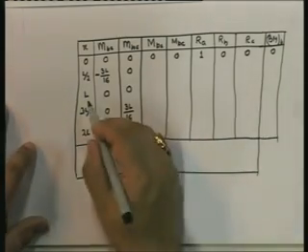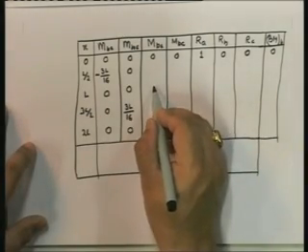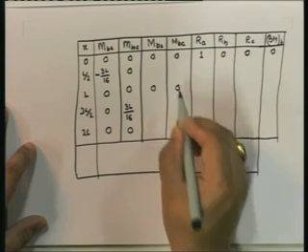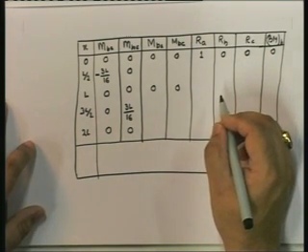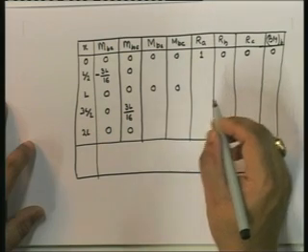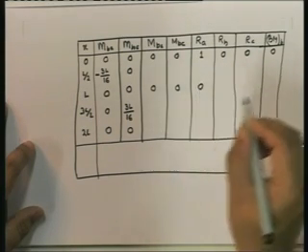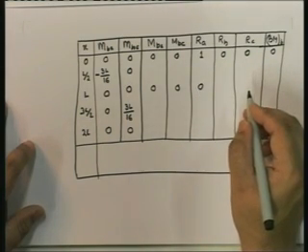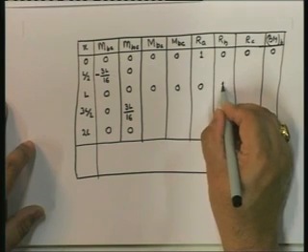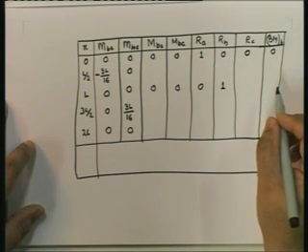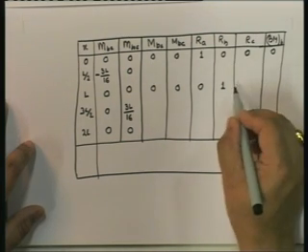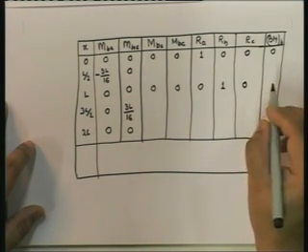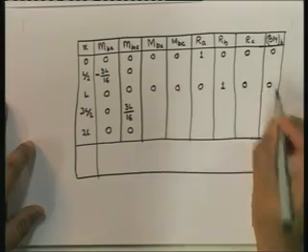Okay, let us now find it out for this. Obviously MBA and MBC are equal to 0. RA is equal to 1 minus x by L. X by L is 1, so this is 0. RB is equal to x by L, so it's equal to 1, and RC is equal to minus MBC by L, so this is 0, and bending moment is also 0.